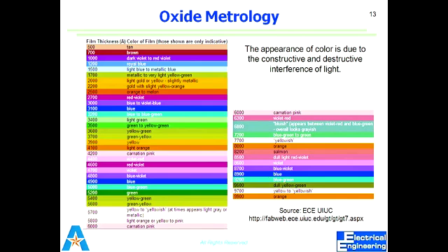So you will see that after the end of the oxidation experiment in the lab, your wafers, which initially were gray because it was silicon only, are now blue. Due to the oxide, they are royal blue or light blue, just like sky blue. That is because it means it has a thickness of 1200 to 1500 angstroms of oxide.